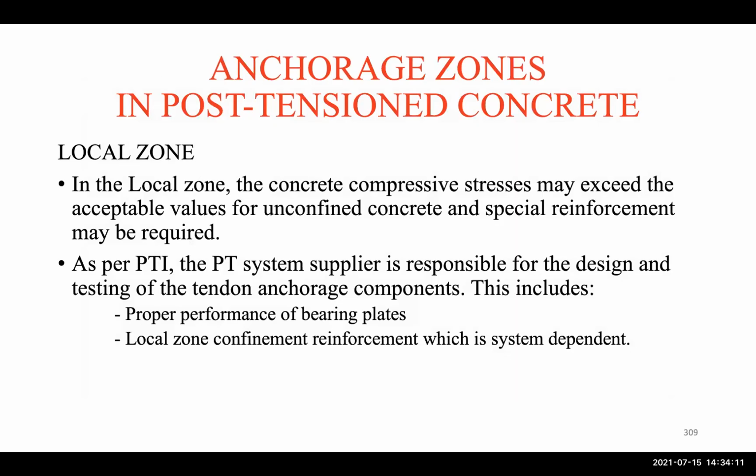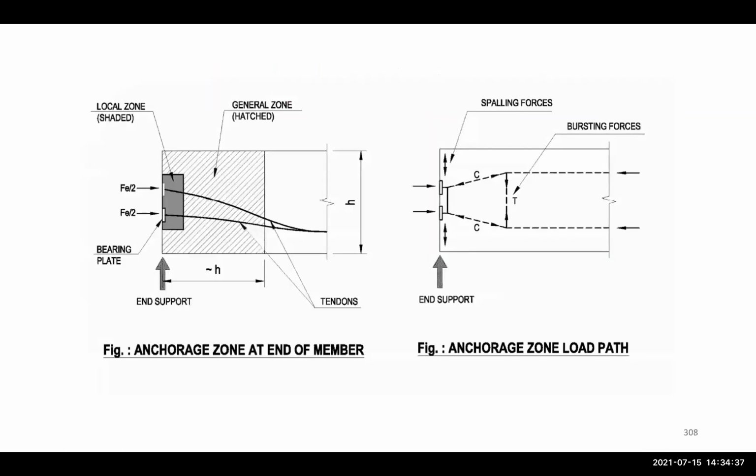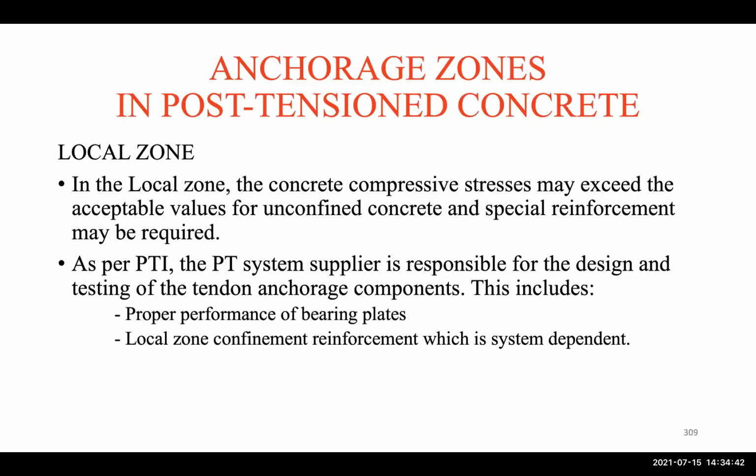The local zone will experience, of course, high concrete stresses, and then, of course, tensile stresses. Whenever we have tension, then we have a problem with concrete, correct? So we have to provide reinforcement at those locations. And the bearing plates that we have here, where the forces are applied, of course, have to be designed properly.